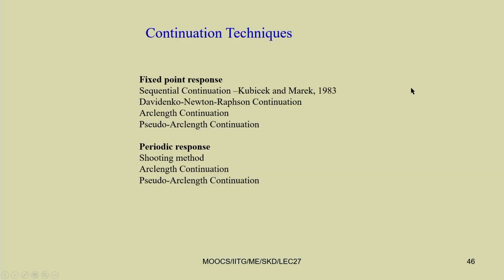For fixed point responses you can have the sequential continuation technique or Keller's method, developed by Keller in 1983. Then there are Newton-Raphson continuation and arc length continuation techniques, and the pseudo arc length continuation technique. For periodic response you can use the shooting method, arc length continuation method and pseudo arc length continuation method. For more details, you can see the book by Nayfeh and Balachandran on applied nonlinear dynamics.